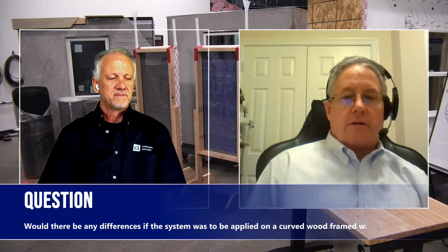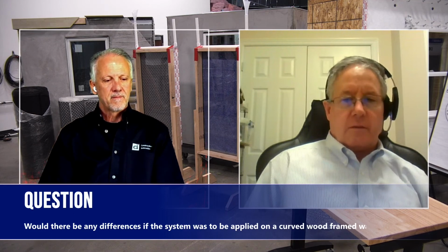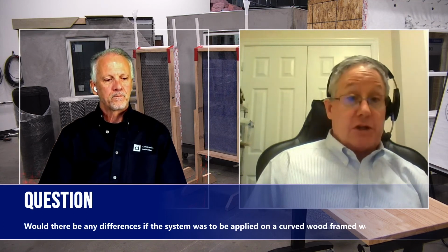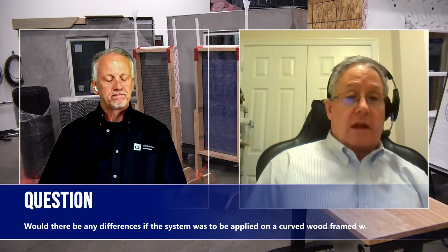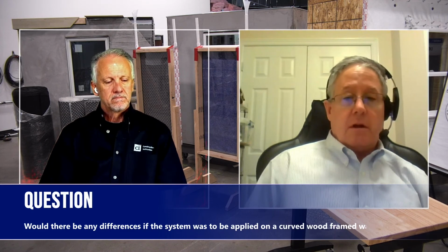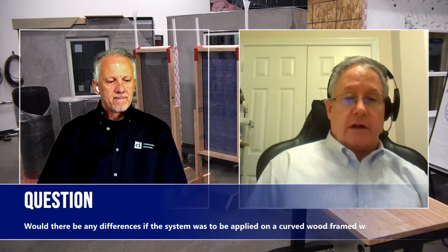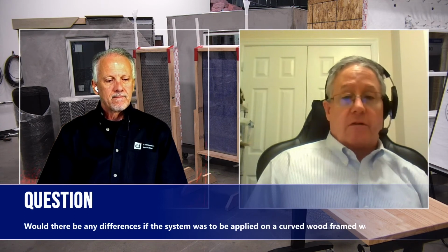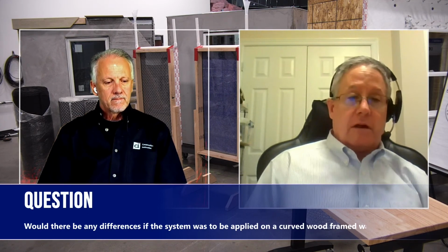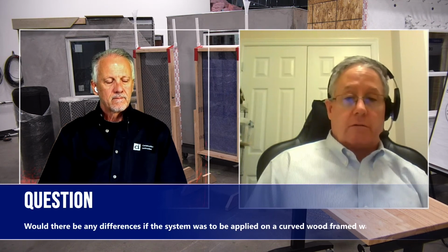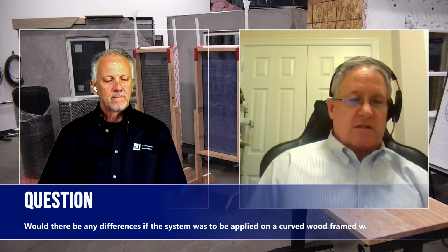Great question. And you touched on another detail that people often ask, and that's expansion joints. Yeah. In many cases stucco needs it. That's all installed right in front of the Delta Dry. You don't have to install it back to the substrate and then muck with the dry around it. You just install it in front of the dry. So it doesn't really change anything.